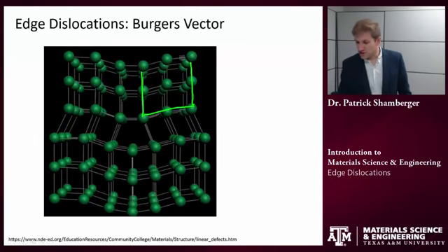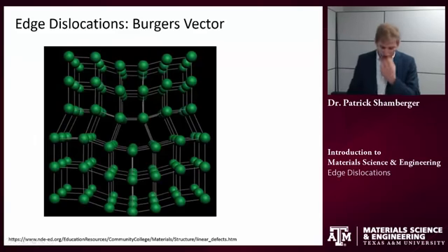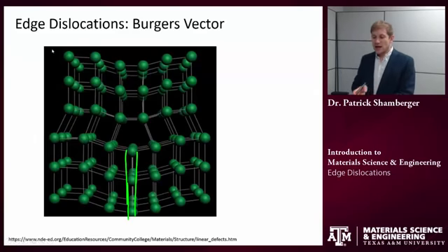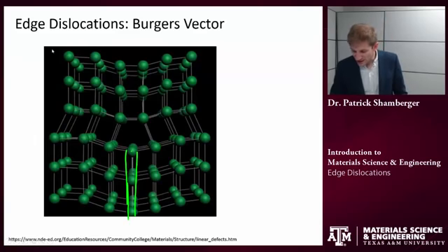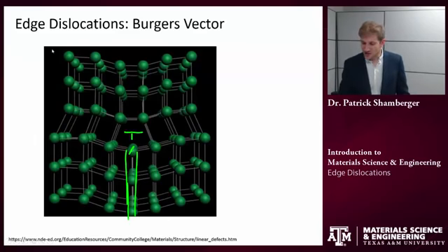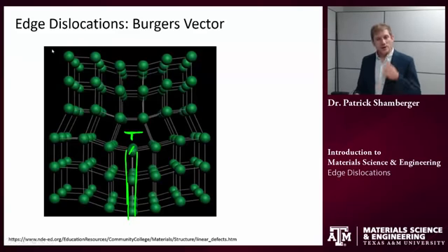So the first thing that we need to do is identify the dislocation itself. If you look closely, you see there's an extra half a plane of atoms here. And remember, the edge dislocation is the linear defect that forms the boundary of that extra half a plane. So if I connected these 3 atoms in a line, that is the edge dislocation. It's a line that's extending into and out of the plane. The symbol for an edge dislocation looks like a T, where the lower prong of the T is pointing towards that extra half a plane of atoms.